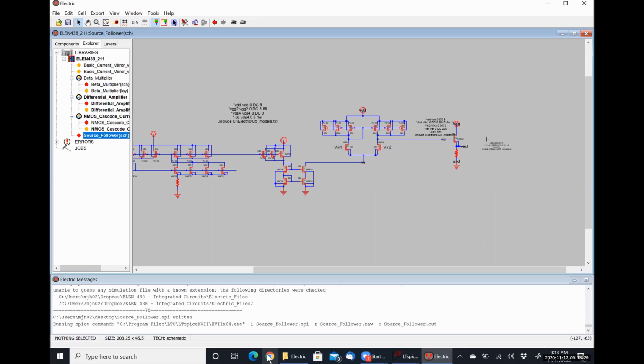So yeah, I had actually suggested something like that to Kurt. How a wah-wah pedal works, and the reason why, I mean, they can be expensive, but they're not nearly as expensive as if they had to use a tunable capacitor or a tunable inductor, is it's a potentiometer whose post is set on a gear, so that when you rock your foot up and down, it rolls that potentiometer forward and backwards. And that is moving the resonant frequency of the circuit up and down. So that is very similar to the frequency control you guys want.